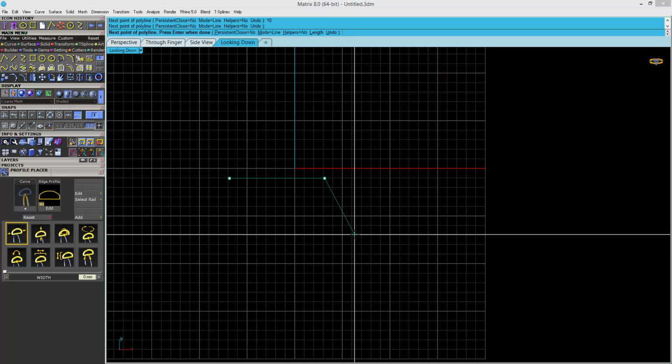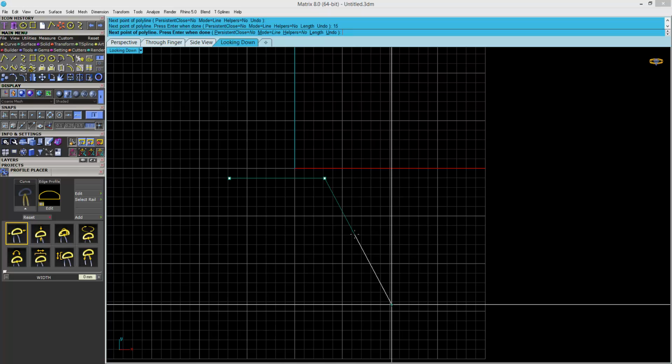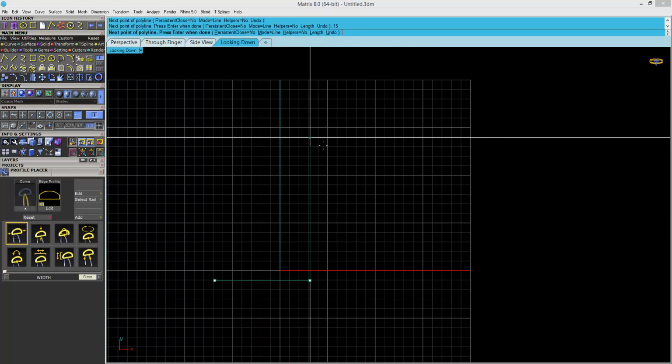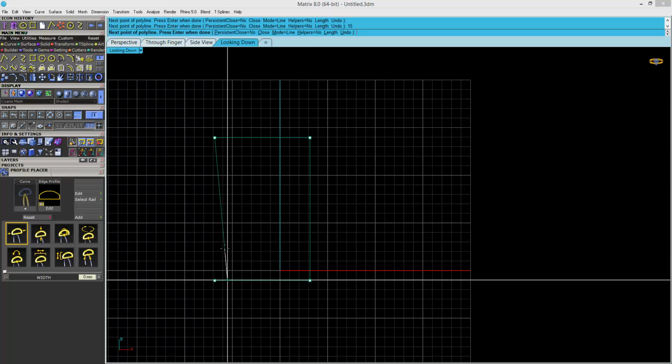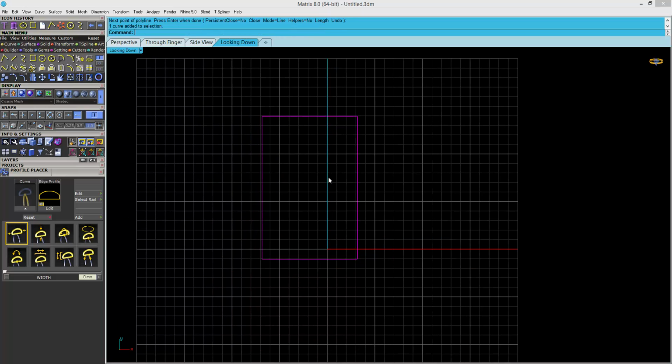So this way you can go ahead with your design, like 15 millimeter up, use shift, and then go here again 10 millimeter, shift, and then go down again 15, shift. So here you have, yeah. When you have the design and you have to do it, how will you decide, like for this ring, how many millimeters you have to take here? All the information will be given with the design. Yeah, all the dimensions, the diamond size, the ring size, everything will be given.